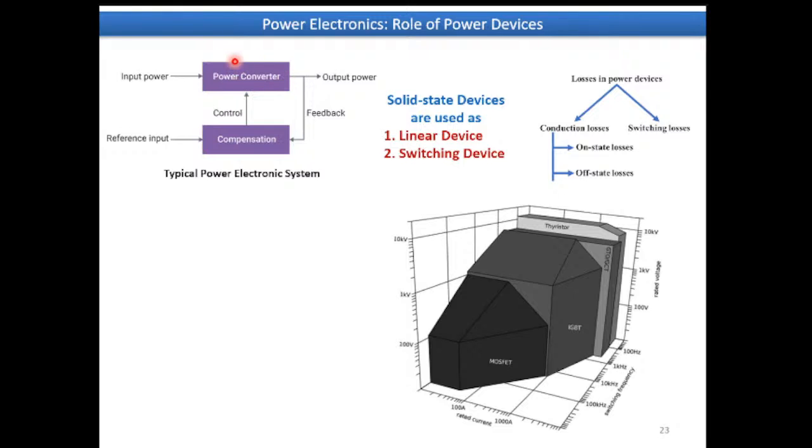Okay. So if we can operate our power electronic system or our power devices at very high frequency, then the other associated component size will reduce and their efficiency will increase. With the increase in the frequency, we get two advantages. One is the efficiency, that means all these losses will be less, and another one is the cost. Because if our power electronic size is getting reduced, overall material cost and production cost will reduce. Efficiency and cost are always the main driving factors for our engineering research. With high frequency, we can do that, high frequency power devices.